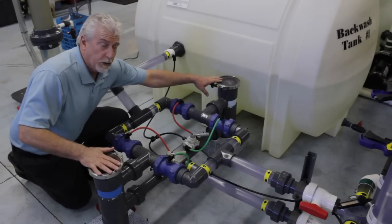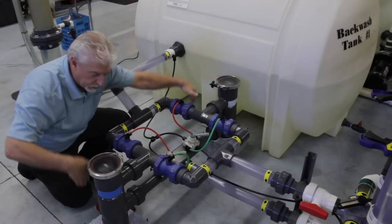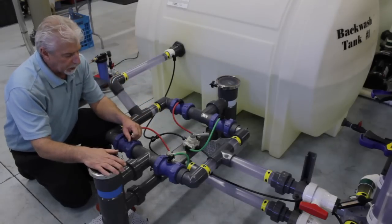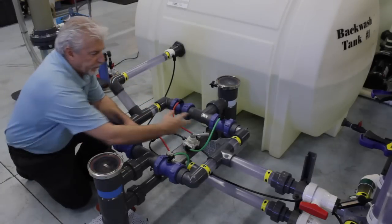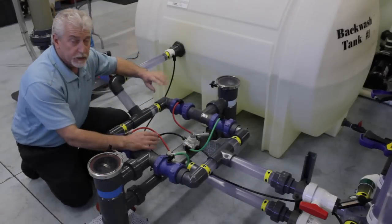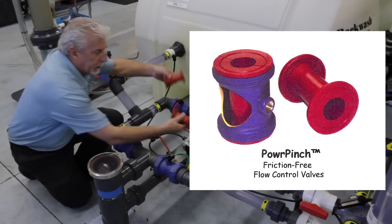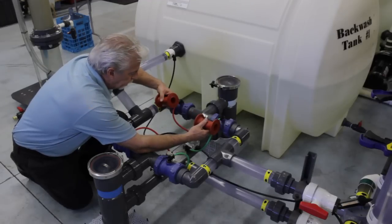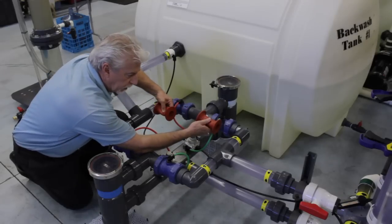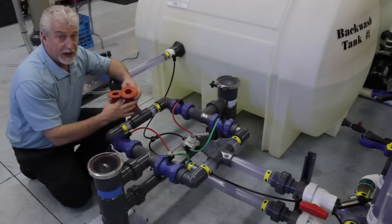We've got air in the water so you can see the flow coming in, being split onto the 2 filters, through the 2 filters, back to a collector line, back to the system. So what we're going to do is stop the flow into the first filter and open to the waste line. This has to happen real fast, fast valve action, so we accomplish this with rubber pinch valves. Normally this one's open, this one's closed, and when I go to backwash it by actuating the actuator valve, it's going to pressure this one closed and open this one to the waste line. Gives me real fast action.